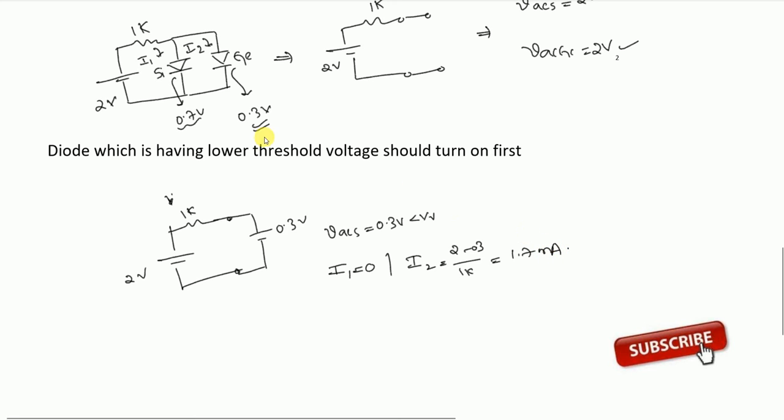This is a very important question, guys, in IES exam and some PSU exams and state exams. See what you should do when the VAC is equal: you should check the threshold voltage, and the diode which has lower threshold voltage, you should turn that on first and check VAC across the other diode. So is this okay, guys?